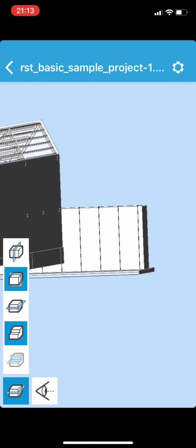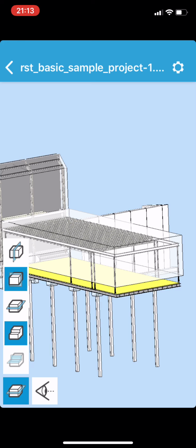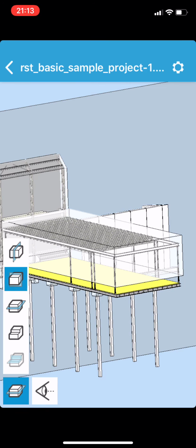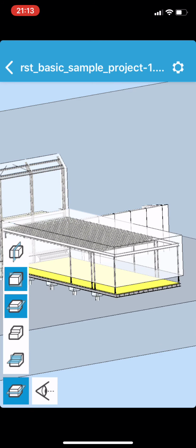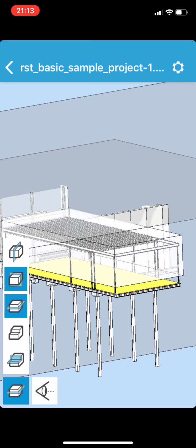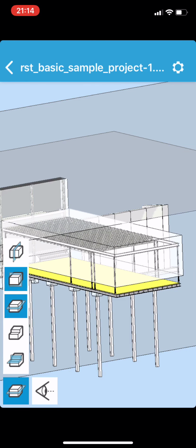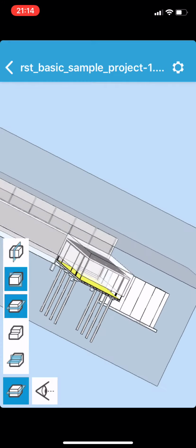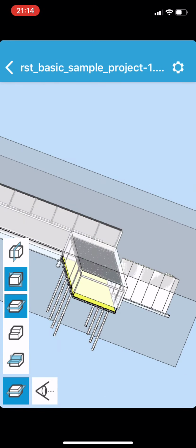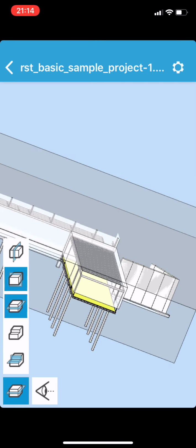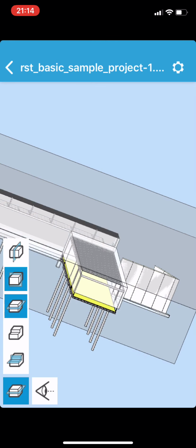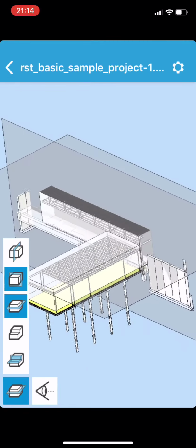And so what I'll do is I'll tap that off, and I'll leave the plane on for a second, and now that'll be cutting it that way, in the Z-axis. And now one thing that is quite remarkable is that we've got two sections here, and so you can cut this in both ways at the same time, which could be quite useful.